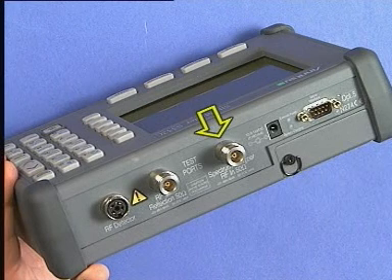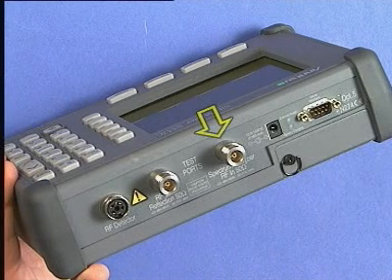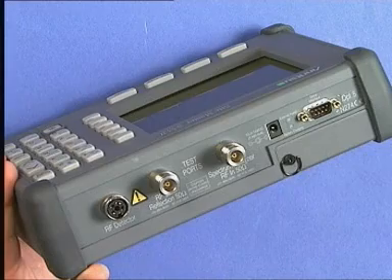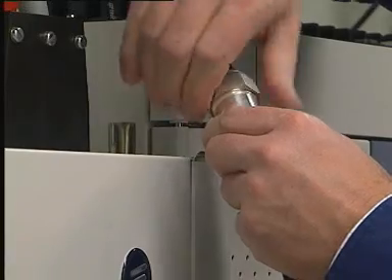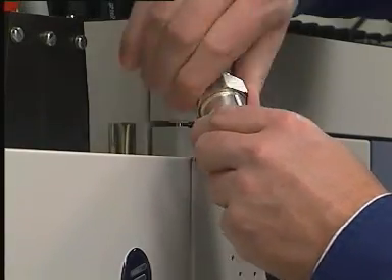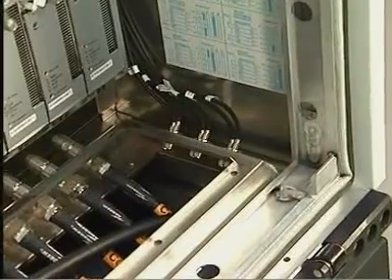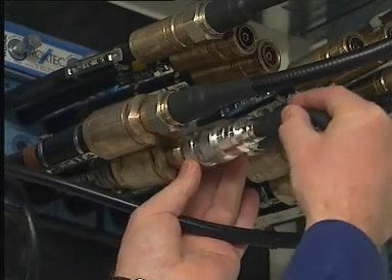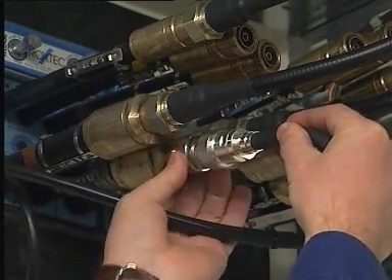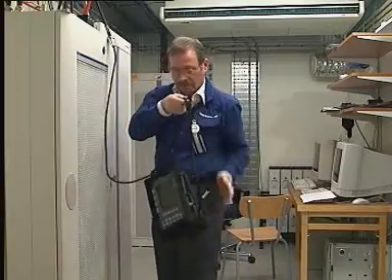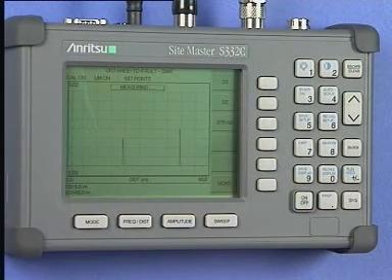Connect the sitemaster's extension cable to a spare antenna. You could use a spare antenna from the radio base station, a convenient receive antenna outlet, or another antenna that is not in use. We are not really too concerned about the actual signal level, just to identify it and decide if it is excessively strong.